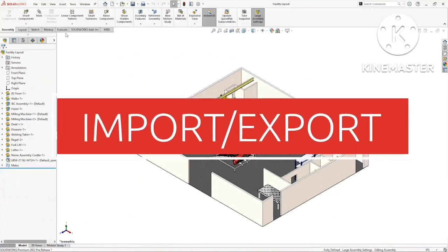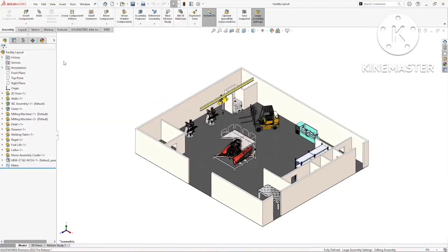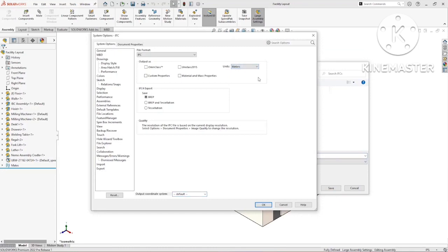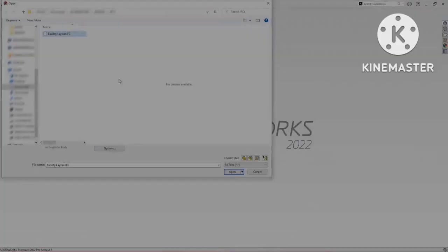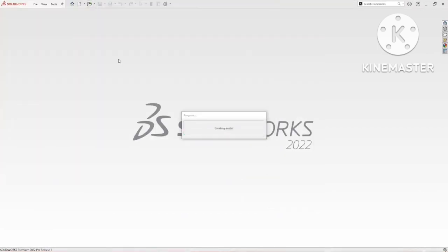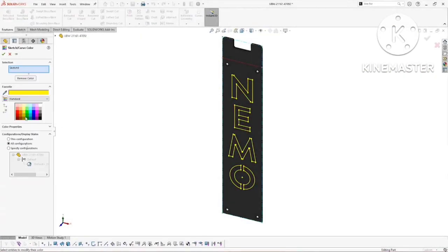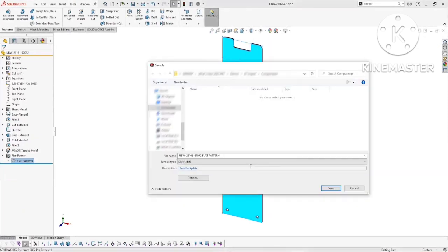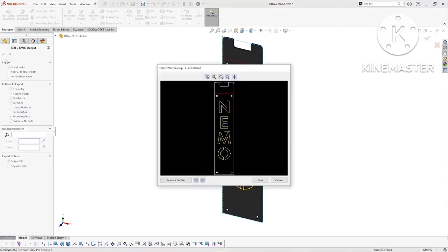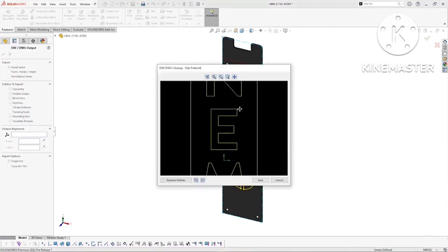Collaboration is key to successful design, as SOLIDWORKS 2022 focuses on improving the reliability and efficiency of saving IFC file formats for other design tools to utilize. There's also a marked improvement in reading these IFC files this year with the introduction of selection boxes on import to let you remove unnecessary data and integrate more effectively with BIM. Along with the improved import performance for thousands of bodies, DXFs and DWGs can be exported directly from part files with colors already assigned to lines, allowing you to get your parts to manufacture faster than ever before.